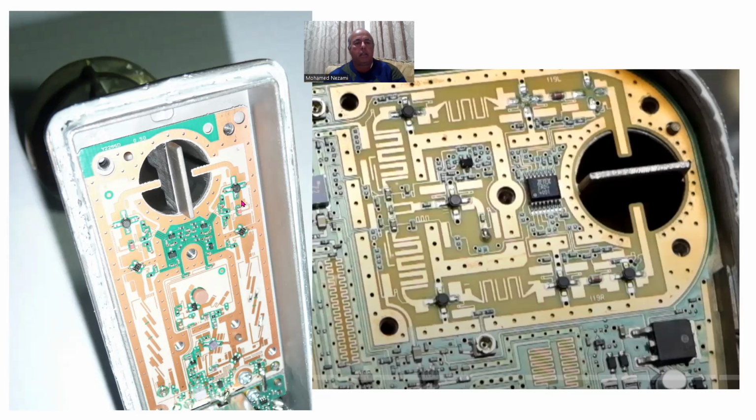You can see in here that it goes in and basically has separate processing, amplification, and filtering for vertical and horizontal. And you've got a bunch of control circuits in here where you program either horizontal or vertical, depending on which one you bias, this side or this side. That's what you see in here, power regulation and biasing and all that. You can see it also in here, okay? And you can see that here's one branch and here's one branch of the low noise amplifier.